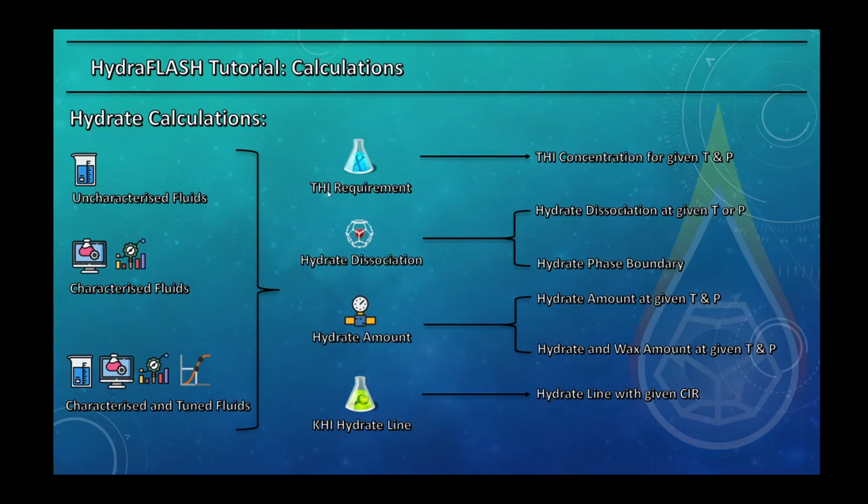The next module is a THI requirement. THI stands for thermodynamic hydrate inhibitors. And by requirement, it means that, imagine that you are working at a temperature and pressure, and at those conditions hydrates are stable.